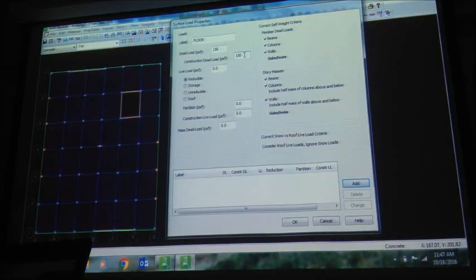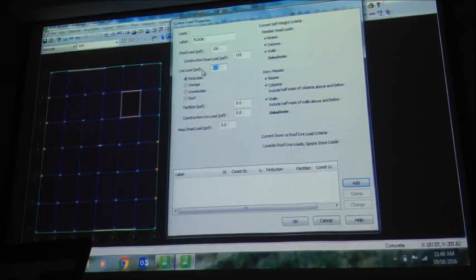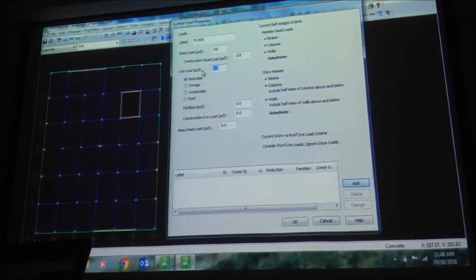Again, usually if your dead load is 150, your construction live load should be 125. Well, why don't we do that, 125? Live load, it's a floor, so maybe 60 psf, office 50 or 60, right? Let's use 50. Is that reducible? Yes. If it is at the roof level, you can click on the roof, then it will reduce according to the roof's equation.